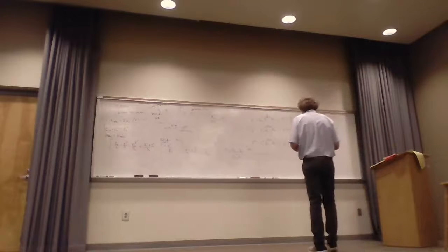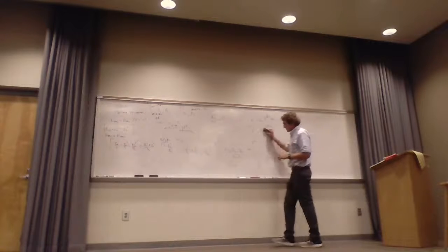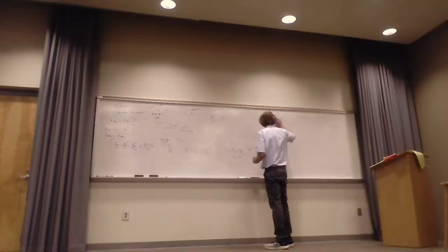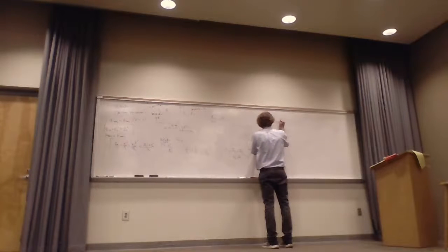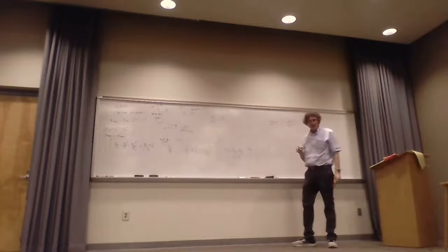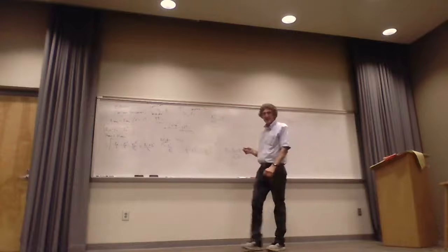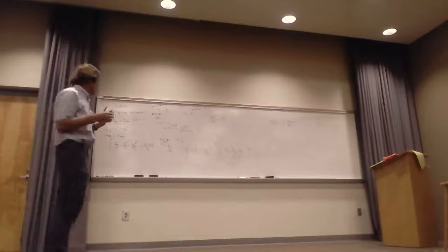Furthermore, I will also mention the standing wave ratio. You remember what SWR was? I just got done teaching this to my other class. The standing wave ratio is really E max over E min in the phasor domain for propagating waves. Do y'all remember that? Back in the day, you had V max over V min on the transmission line. It's the same deal here. And here's what's going on.